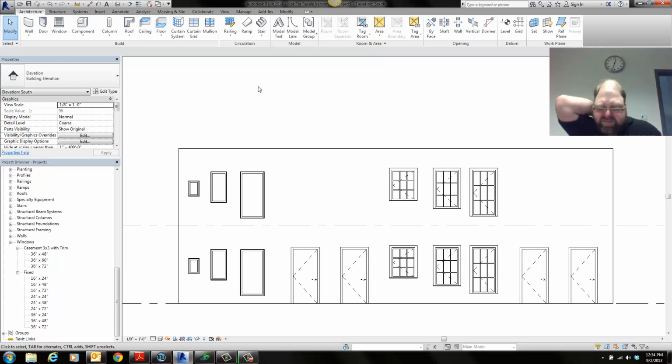This behavior, this change, is also part of that. I talked about design intent, for example, last week, and I talked about relating roofs to walls and things like that, and I've talked about it a few times probably. But say, for example, design intent, this casement window: the design intent of this is that it's supposed to have a 3 by 3 grid in it no matter what.